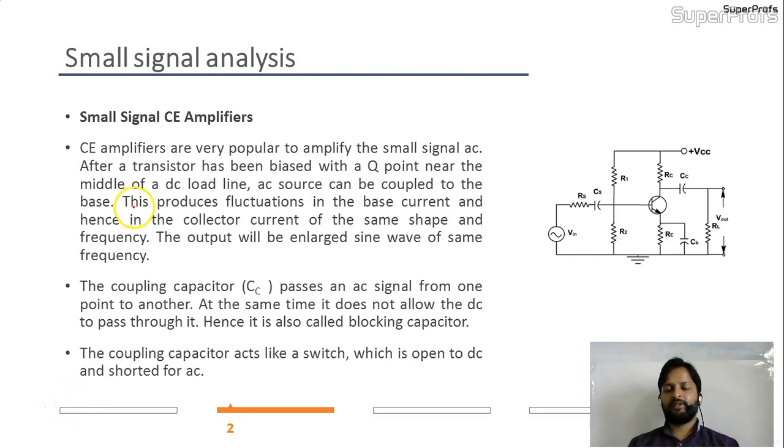Friends, actually what is going on over here, I'll tell you first, then we'll come to the theory part. This circuit is the potential divider biasing. We have chosen one biasing. Why are we choosing a potential divider? Because the potential divider provides us better IC stabilization. What is our motto in using biasing? Our motto is to stabilize IC, the collector current. We need constant current at the output, so amplification will be better, right? So the potential divider biasing is good for that.